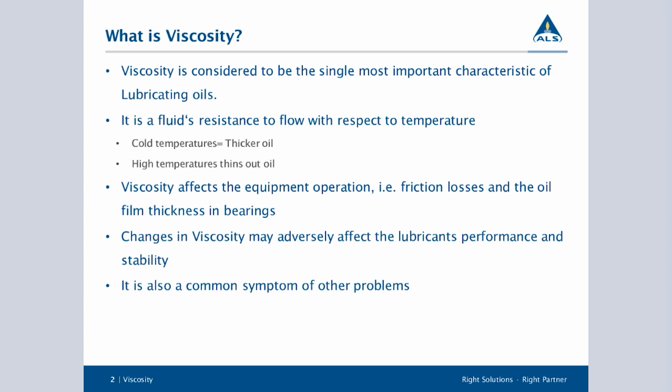When we get into mixed, that means your equipment has been running, and you start to see that thickness increase. When I say thickness increases, there's a separation being created between your 2 components, and you see more sliding going on and less friction. When you get to hydrodynamic, you're seeing a full film layer of oil support, and that's also at full speed conditions, and that's what you're really working towards. The reason I go into this oil thickness is that's how you decide if your oil is working correctly, as well as if you selected the correct oil.